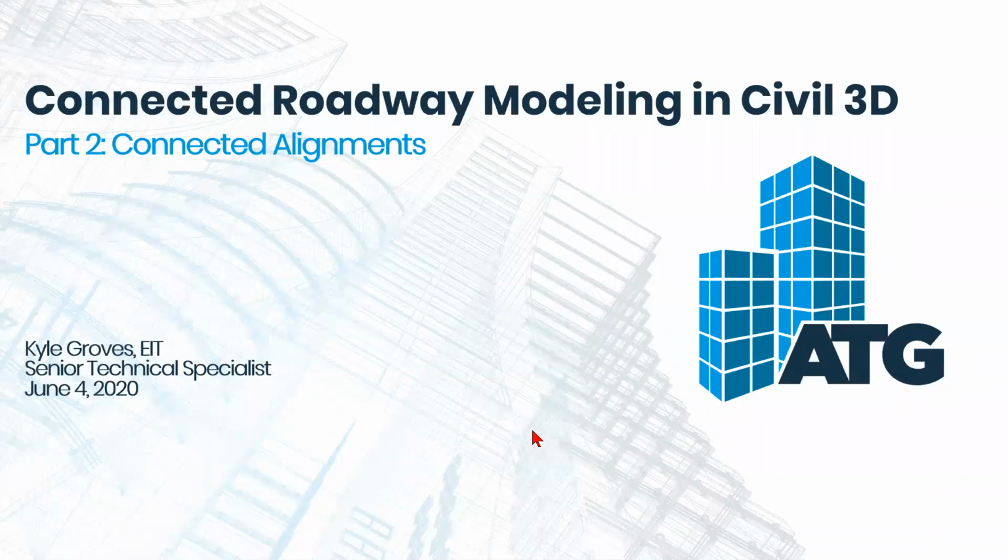So we're here today to talk about connected alignments and just alignments and profiles in general, because alignments and profiles are really well functioning baselines for our corridor models. That's what our assemblies attach to. That's the 3D path that our typical cross-section follows, as well as target objects. So even if we're not using this as a starting point for our design, they give us really fine-tuned control over all of the different ways that we can modify that typical cross-section that is defined by our subassembly. We can be narrower or wider, steeper or shallower for any one of these model elements that we want to use that targeting for.